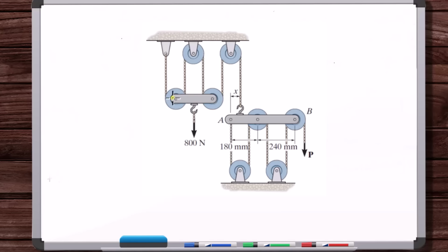If you had a pulley that was really rusted and it's trying to roll, there's a couple moment that's resisting the rolling. Or if that pulley was holding up a load, there's a couple moment helping to hold up the load because it's preventing the roller from rolling, right? A frictionless pulley is saying that this is perfectly smooth. There's no couple moment in the roller, okay? That term doesn't have anything to do with saying that the friction between the rope and the pulley surface is frictionless.